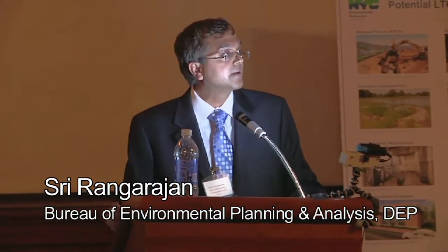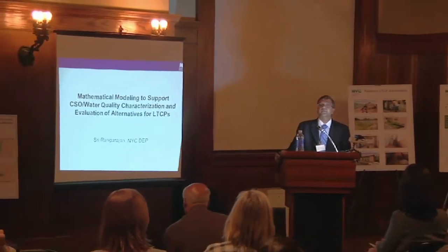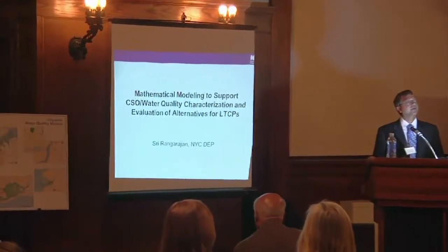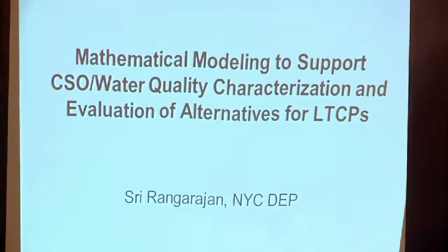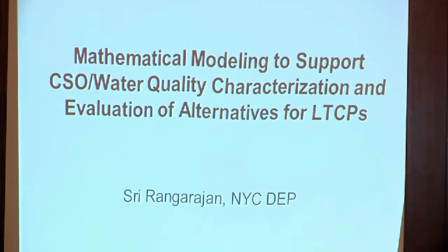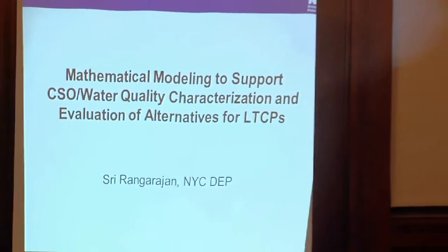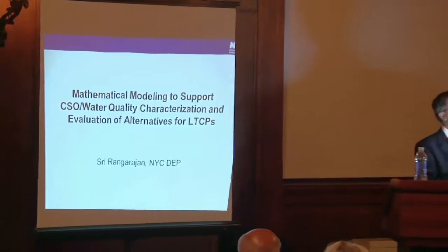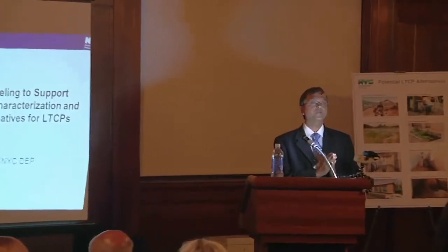As Gary mentioned, and also Linda followed up, the mathematical modeling is the backbone of our CSO control program. Why do we do mathematical modeling? We could actually construct a project like a retention basin, follow up with post-construction monitoring to understand the improvement in water quality that we get out of this project. But it's a trial and error process. You need to be able to construct a lot of it and then monitor each one of them.